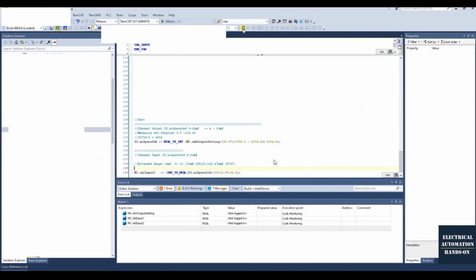This comes from one short test video. In this short test code, we can see this line, that is the analog output. And this channel is 0 to 20 milliamp. I'm going to output 4 to 20 milliamp. And this set point range is 0 to 100%. And here it should be 6553. Sorry for this, there's one typo. And this is an unscale equation. This channel is 0 to 20 milliamp, but using this equation, we will output 4 to 20 milliamp.